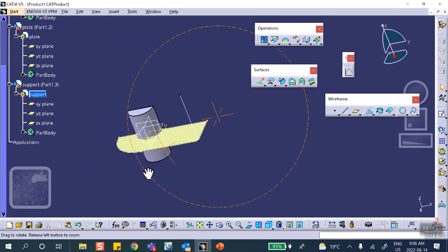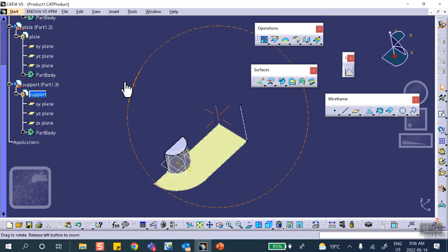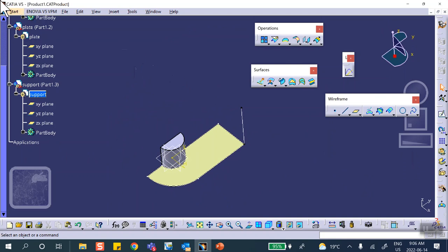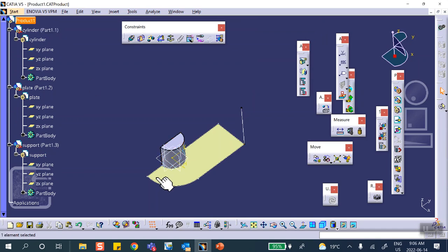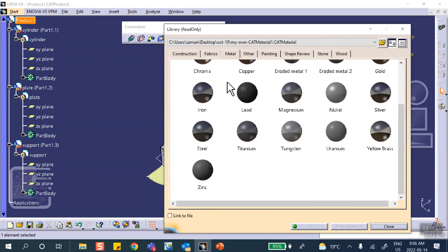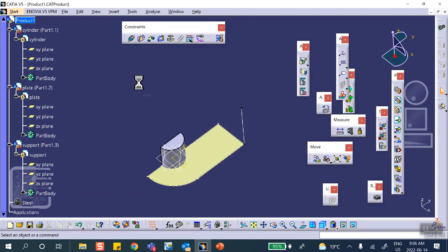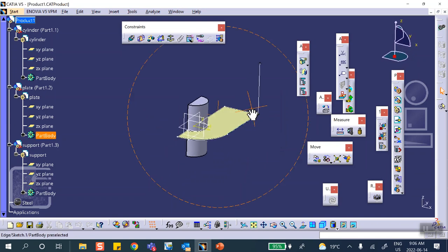Okay, at the end of the day, you have to have something like this, whether it's in a single part or an assembly. Well, I did a single part for you. You go up there and you put properties of steel on it. Properties, steel on that product. Immediately save it. We already saved our product. All we have to do is to click on the floppy and it saves the stuff that we did since then. That's pretty much it.